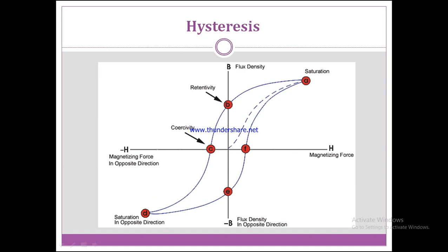The value of the external field is small, that is H is small, and the domain wall movements are mostly reversible. This corresponds to the known reversibility of the initial portion of the magnetization curve. The behavior starts from 0 and goes in the upward direction up to the saturation point, that is at point A.